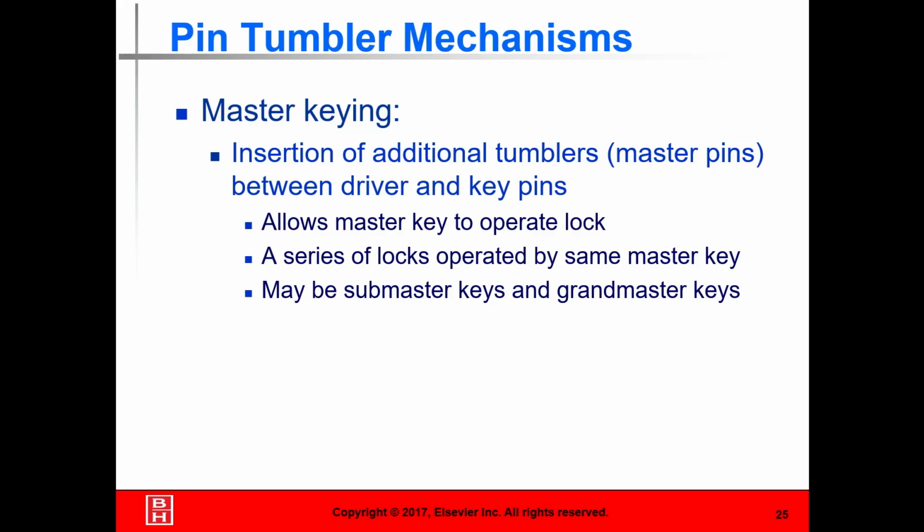A master key is a simple master key system using master pins in the first and second tumbler positions. When the change key is inserted, the remaining positions show the key pins aligned at the top. The arrangement permits a plug to be turned. So the master key is changing the first couple of them and not really affecting all of them, but it allows you to open the lock.